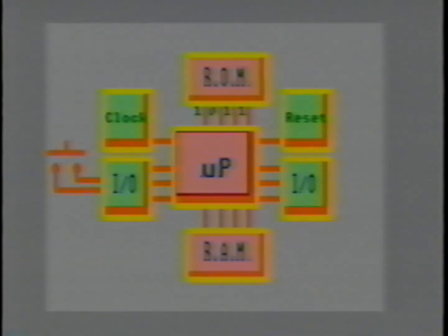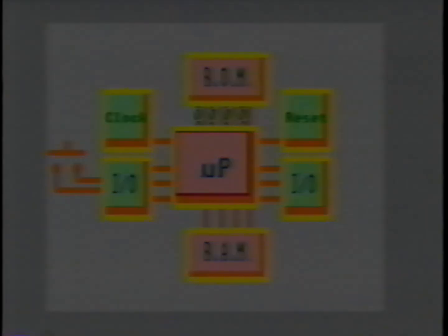The next instruction fetched by the microprocessor is interpreted as an output function. The microprocessor then issues the play signals through output ports, which place the VCR in the play mode and lights the front panel display to indicate the action taken. This fetch an instruction, execute it, then fetch another sequence of events continues as the microprocessor monitors and controls the VCR.